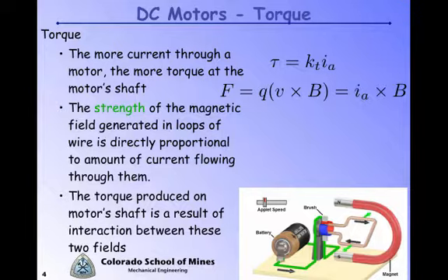And as the equation at the top says, the torque is proportional to the current in the armature, and that comes directly from the Lorentz equation, which is shown below it, which basically says that the force generated is the cross product of the current, in this case in the armature, crossed with the B field, which is the magnetic field in the field windings, or field permanent magnet field.